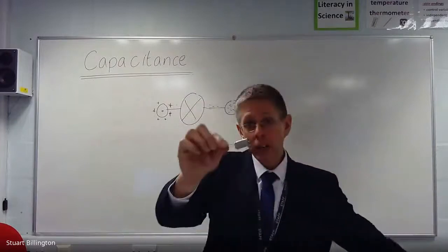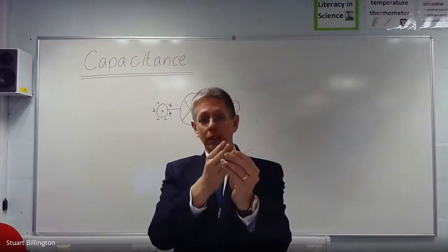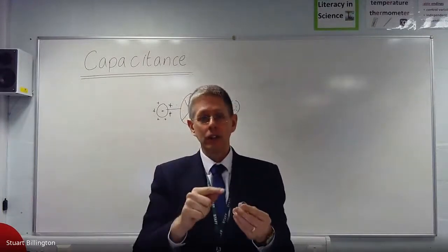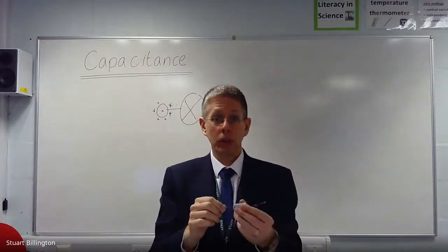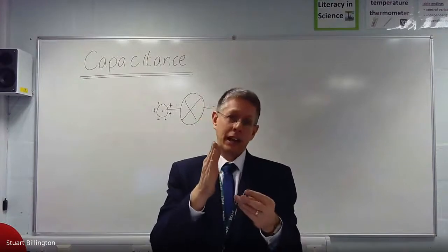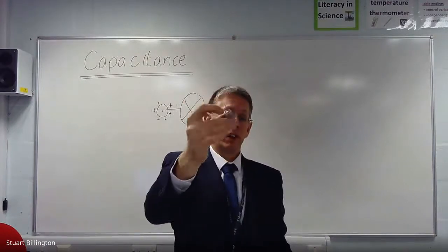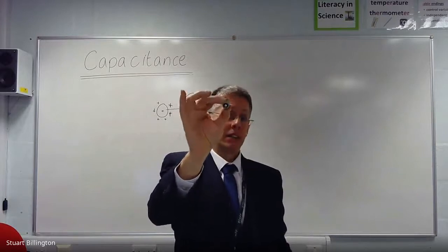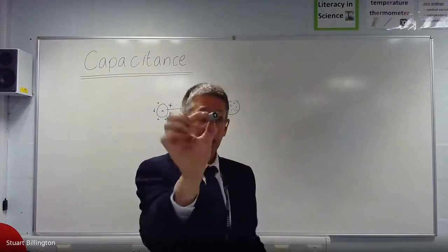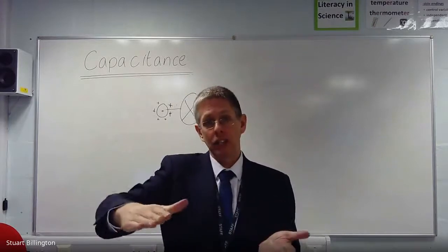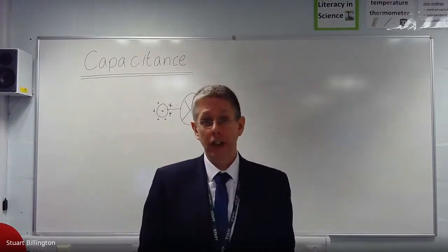We could chop the ends off this and take the casing off the outside, and you'd be able to unroll it, and you'd see that it was kind of like a Swiss roll with layers of dielectric and the two plates all rolled up together to make this compact design of a capacitor. But this cylindrical version is really just two flat sheets that have been rolled up together with dielectric between them.